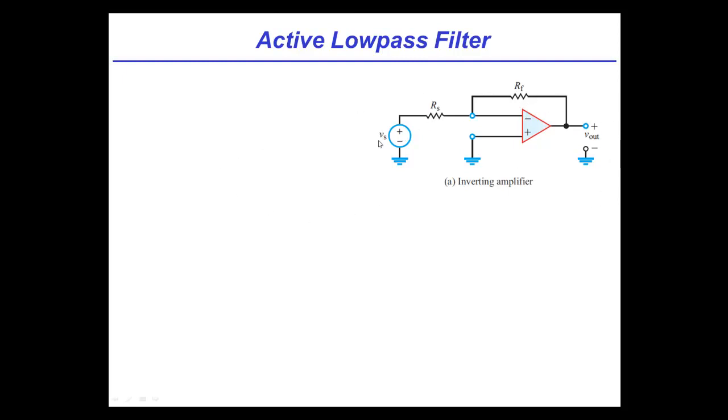So we want to relate Vout to Vs, in other words, find the gain of this amplifier. You know that it's just going to be calculated in this form. Firstly, it's inverting, so there's a minus sign, and it's going to be the resistance of the feedback path, RF, divided by the resistance of the forward path, RS. I remember that from the basic op amp stuff. Right, and that's the case here.